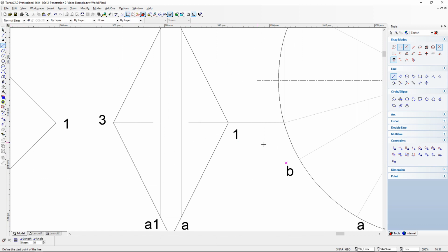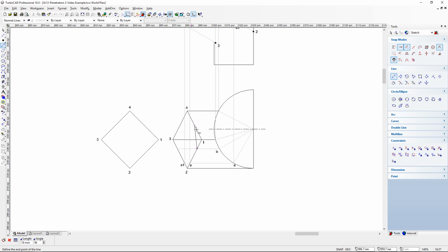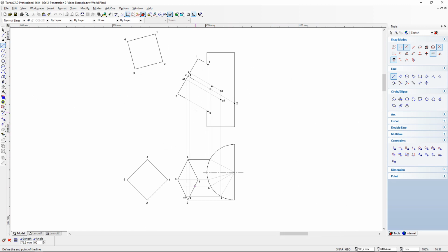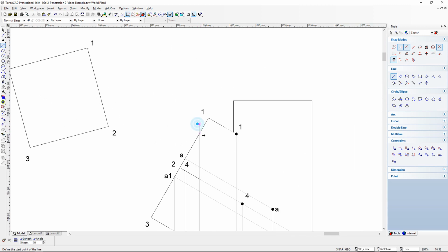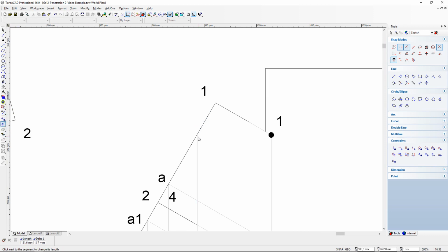We're going to take a light construction line, place it at B, draw the line horizontally all the way through side 1, 2, and 2, 3. And then I'll just shorten it till it hits the edge there. And we're going to do the same as with A, just now number B. I'm going to take it from that side, which is 1, 2, all the way 90 degrees up to where it hits number 1 and 2 on the front view of my slanted prism. And I'm going to cut off the line right there on the edge.